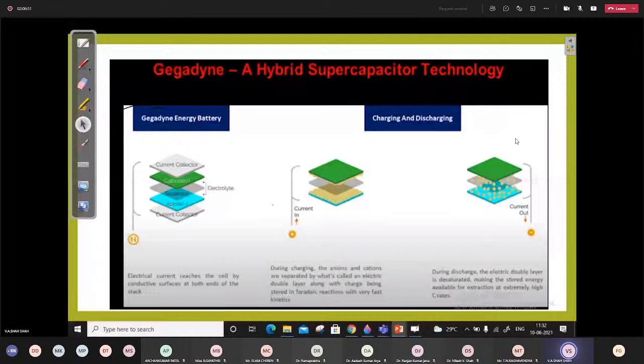Again, in these you also have the multi-phase concept, multi-phase motor, which is very preferable for vehicle application. Suppose you have a three-phase system and one of the phases stops working; then, especially for an induction motor and synchronous machine, you cannot drive your vehicle. If it has a multi-phase motor, then you can have continuity of vehicle operation, but with reduced capacity. So here you will select the motor appropriately for your application.